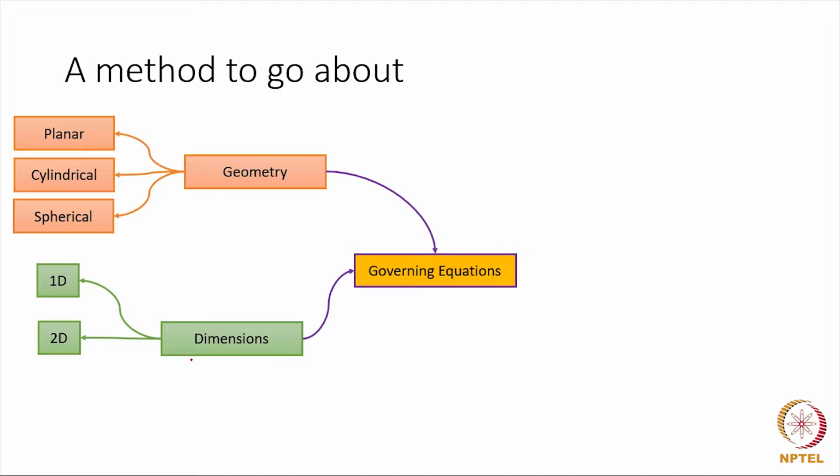And if the problem is such that we have to take a two-dimensional situation, then there will be two terms, which means that we may then go to a numerical way of solving the problem very often. And in a real life situation, we would have it as a three-dimensional problem, and we would usually resort to a full computational solution with a program that will help us in the solution.